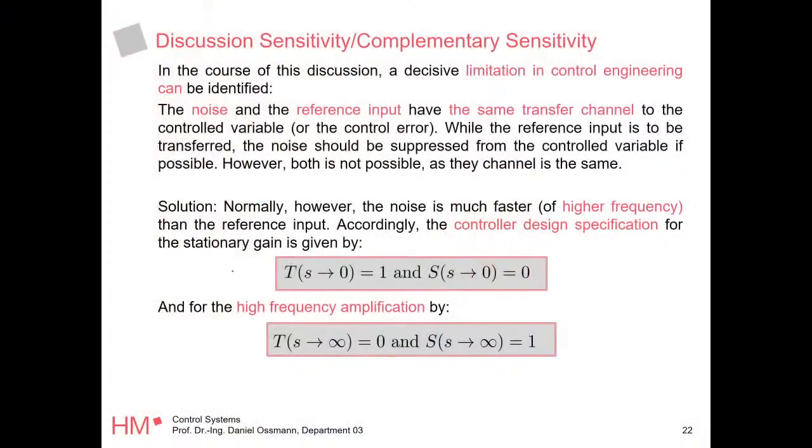And this is really a crucial thing, which I think every second paper I review for conferences, this fails, right? And this is a problem as soon as you go to real examples. If you design a flight controller, we had a flight control design for a UAV where even I forgot it. And suddenly we put the controller on, it oscillated like hell because the sensor noise was amplified by the controller. You always need to make sure that there is no control action at high frequencies. And this is the reason why. Okay, so that's basically it for this discussion.